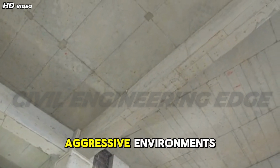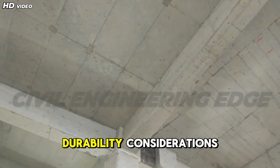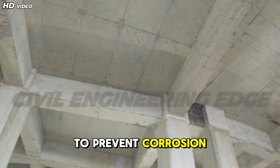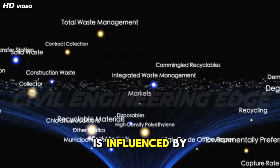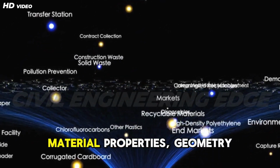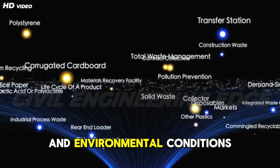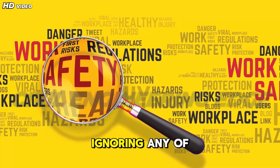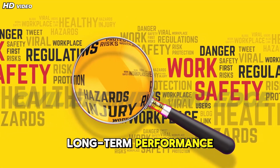Columns exposed to aggressive environments require increased concrete cover and durability considerations to prevent corrosion of reinforcement. Thus, column design is influenced by a combination of loads, material properties, geometry, construction practices, and environmental conditions. Ignoring any of these factors can compromise safety and long-term performance.